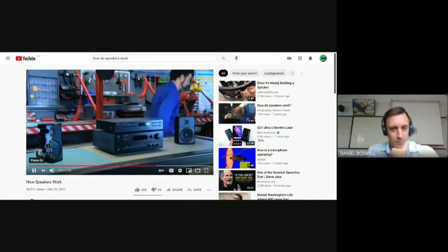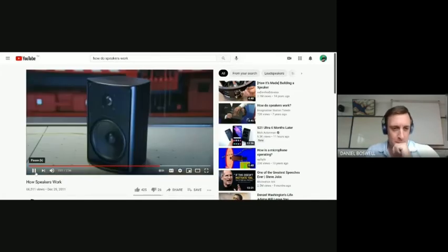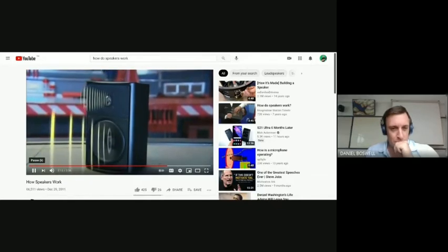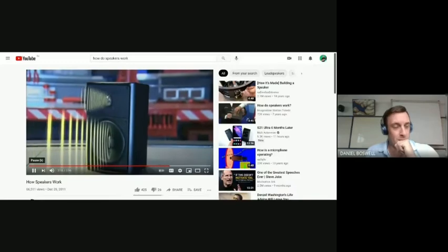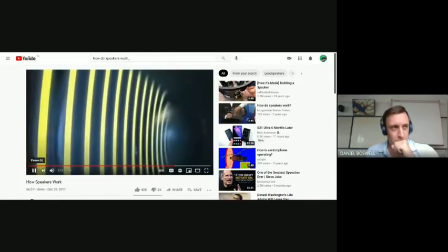Up to 26,000 back and forth times a second. Okay, so we're looking at 26,000 movements per second, which is pretty fast. How often the direction of the current changes depends on the sounds the speaker is required to make. Low notes will get the current to move back and forth about 40 times in 1 second. That means the diaphragm will vibrate 40 times in 1 second.